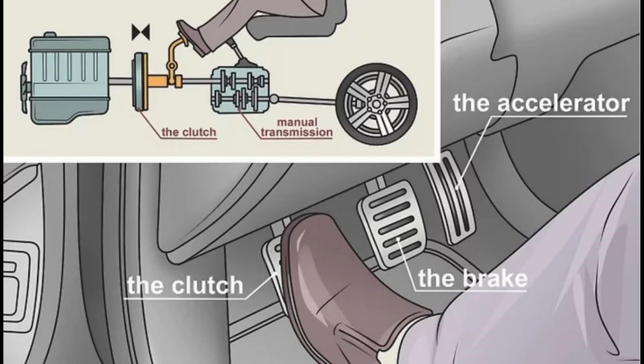At this stage, the engine runs at a lower speed compared to earlier gears, resulting in quieter operation and improved efficiency. Fifth gear, often referred to as an overdrive gear, is designed mainly for fuel economy. It allows the vehicle to maintain high speeds on highways while keeping engine revolutions low, which reduces fuel consumption and engine wear. In vehicles equipped with a sixth gear, this gear further enhances fuel efficiency and driving comfort during long-distance travel.